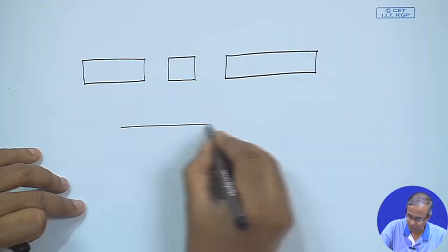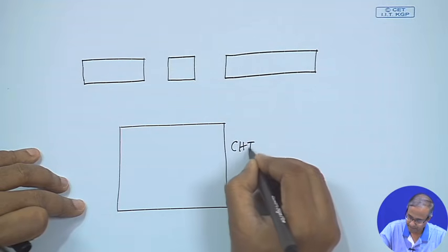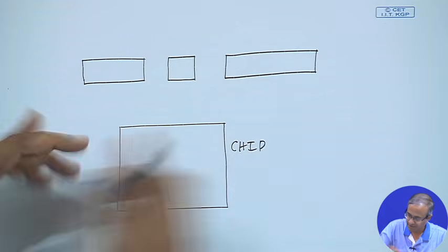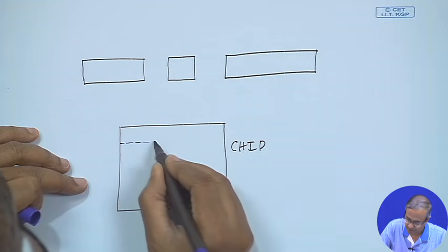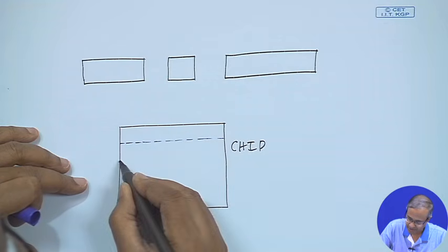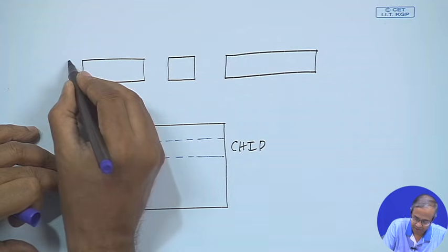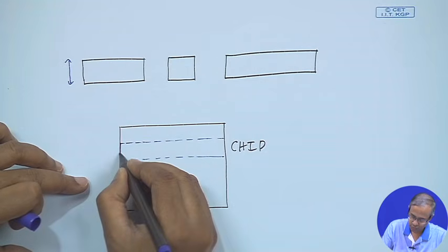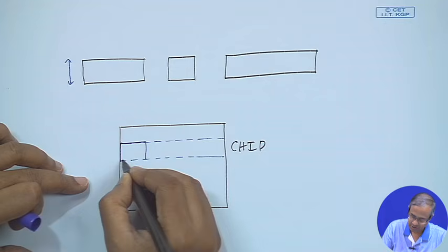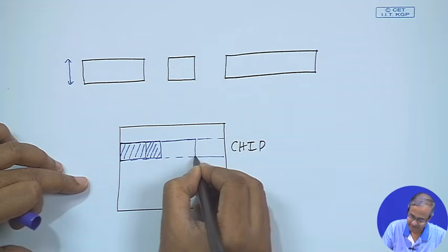When we put these cells on a chip, suppose this is our final chip, here we place all the cells in some well defined rows. Suppose this is one row, the height of a row will be equal to the height of this cell, and within a row what we do? We just place the cells one after the other, they will be physically touching each other, like this.